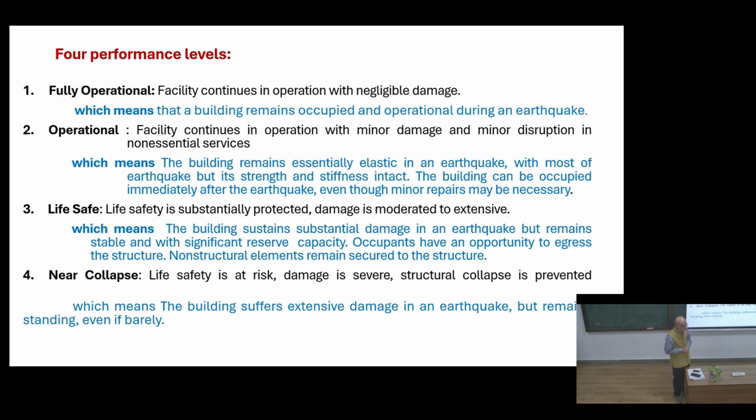Service becomes equally important; the performance of the non-structural element also becomes important. When we say operational, what does it mean? The facility continues in operation with minor damage and minor disruption in the non-essential services. What does it mean? I wrote specifically for you that the building remains essentially elastic in an earthquake.